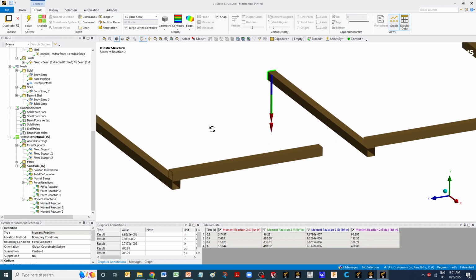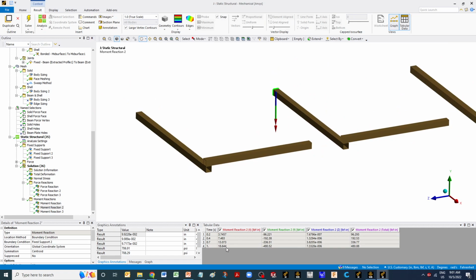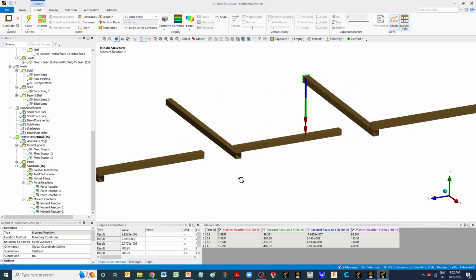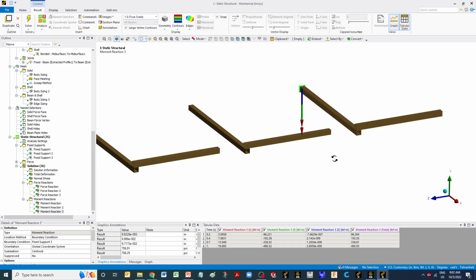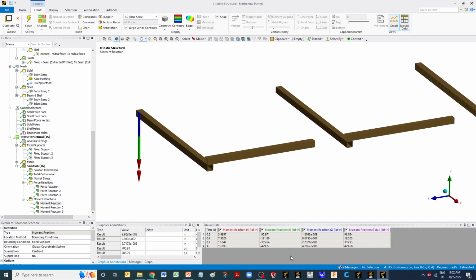Same is true for the shell model. It's showing me a value which is not close to 20, but that's okay, within the numerical accuracy of FEA. But it has more to do with the deformation of the structure as it's being loaded. So the direction of force changes. Just keep in mind we are using the large deformation option. The y component, which is the largest component, which is along this coordinate direction, this axis here in the global coordinate system, we can evaluate that as well.